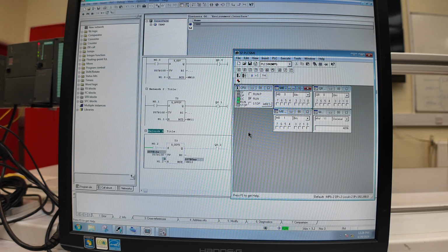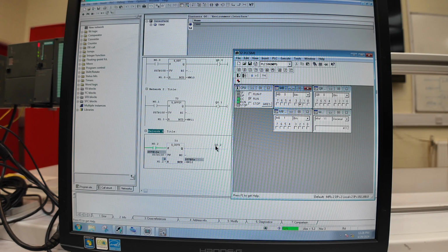So about the last timer, our last timer is reacting to an impulse. So as soon as we give a positive pulse in there, the timer starts running, and 10 seconds later the output will be set. And there's no difference if I'm setting the value to 0 after it got 1 first, the timer is still working. The timer is just changing when I reset the timer first.